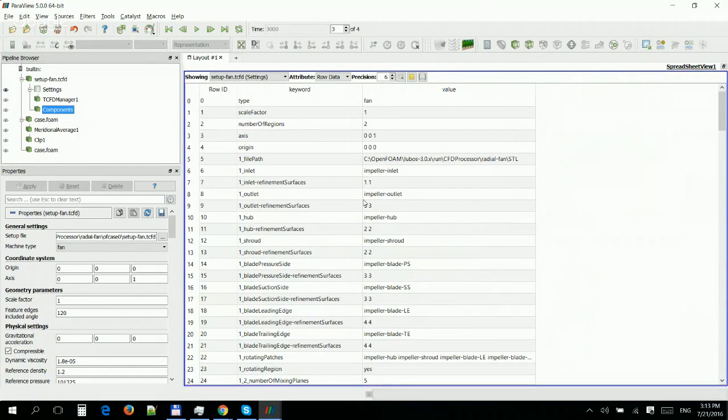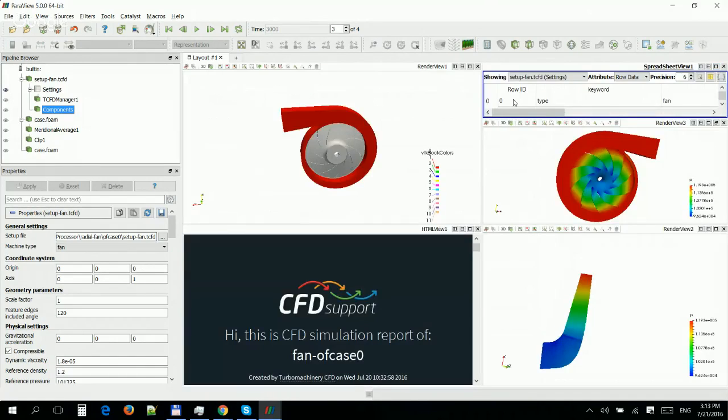It's a single plain text file where all the important information for the simulation is written. So there's always the configuration file and the surface geometry. When starting a new simulation, you can write your configuration file from scratch, or the most effective way is to modify an existing tutorial case to the case you want to simulate. You can just replace the geometry and modify the settings, and you can go.